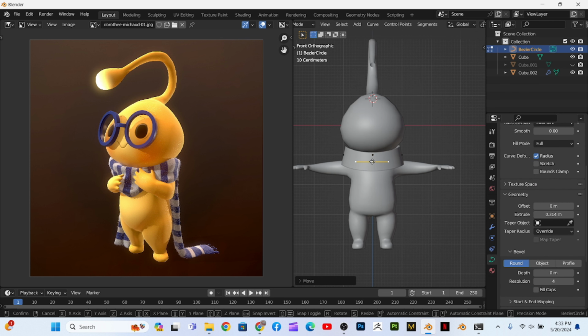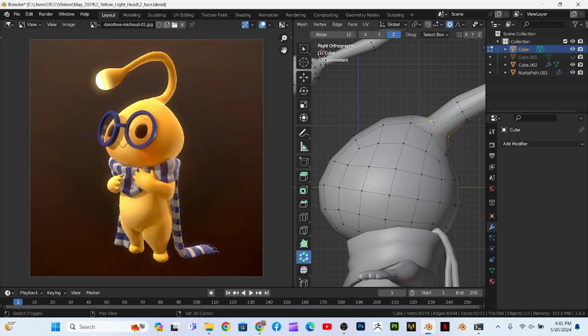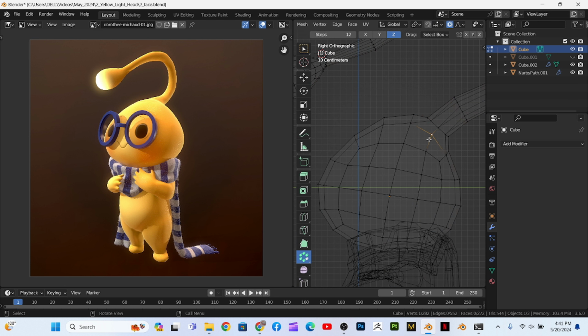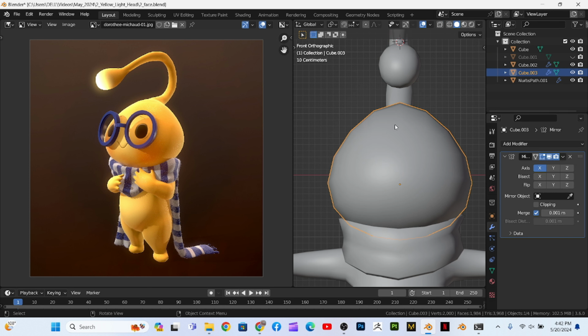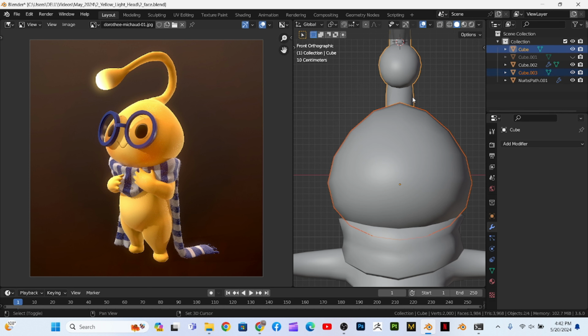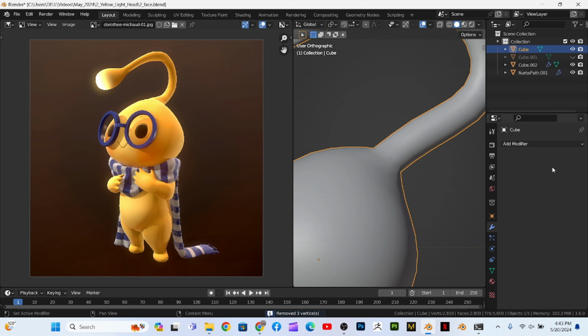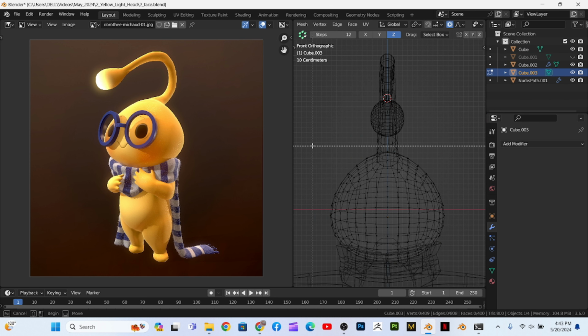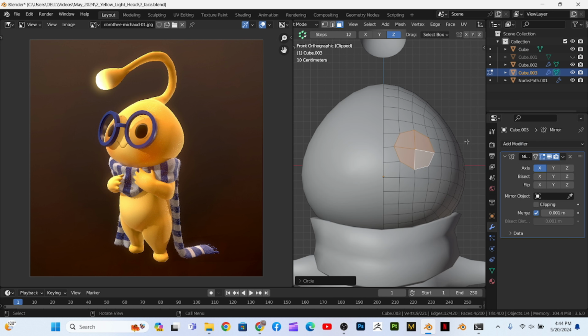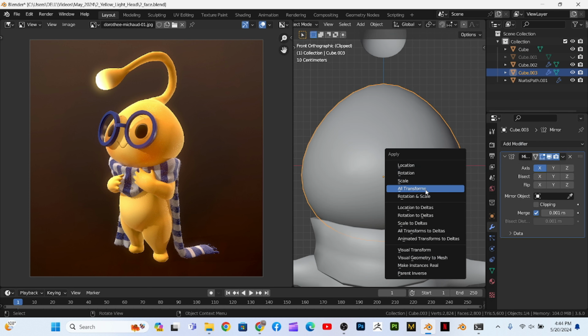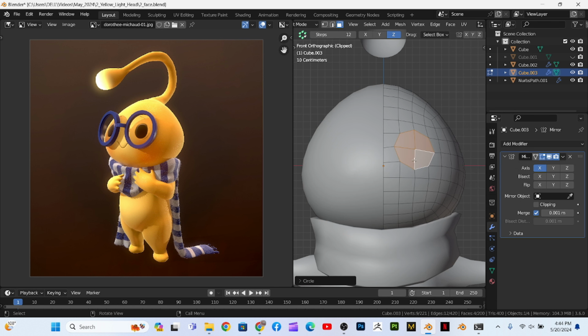Now we will start face detailing. Separate this part of the face mesh by pressing Ctrl P and separate by select option. Apply mirror modifier and subdivision surface modifier because we need the more vertices. Now delete the left side of the mesh and add a mirror modifier. Select these 4 faces of mesh, scale it up and make it circle. Adjust its placement and insert it.